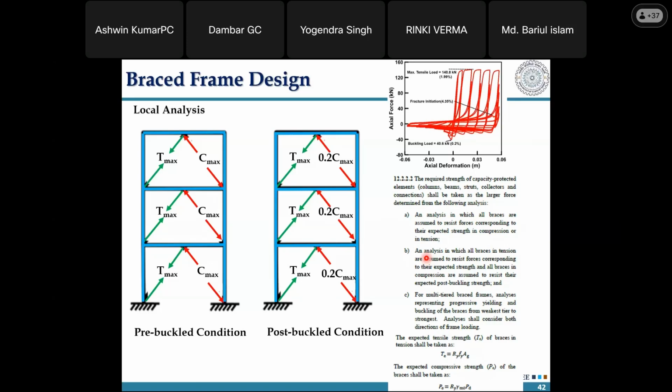Right after this discussion, go into IS 18168, read each clause, and then you'll be able to understand why those clauses have come about. It will be very easy to understand once you understand the fundamentals. Now, with respect to BRBF, you can understand that instead of two braces, you can give only one brace at one floor, and that will be more than